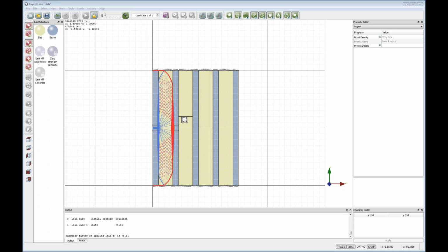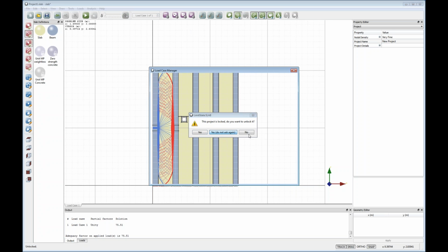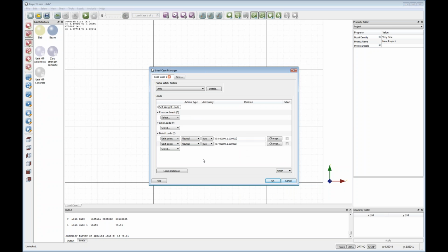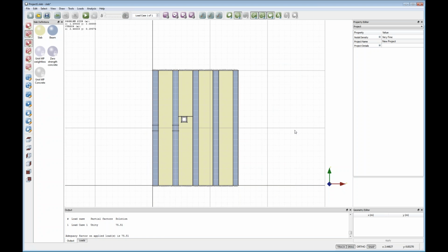All right, I've had another question: could a ground spring distributed boundary condition be modelled? If I understand that right, then what we're thinking about is actually an upwards pressure load from beneath. So all we'd need to do there is go into the pressure loads here, just select that and have it moving upwards rather than downwards, and you should be able to do that.